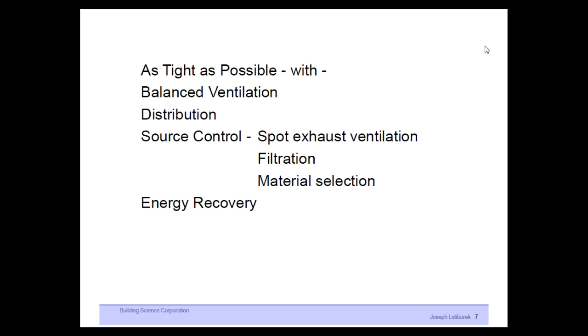So balanced ventilation is the place to go, with some form of distribution or mixing within the compartment or within the building, coupled with source control, spot exhaust ventilation, advanced or enhanced filtration, and materials that don't give off bad stuff. At the very end of this, balanced ventilation makes energy recovery possible.